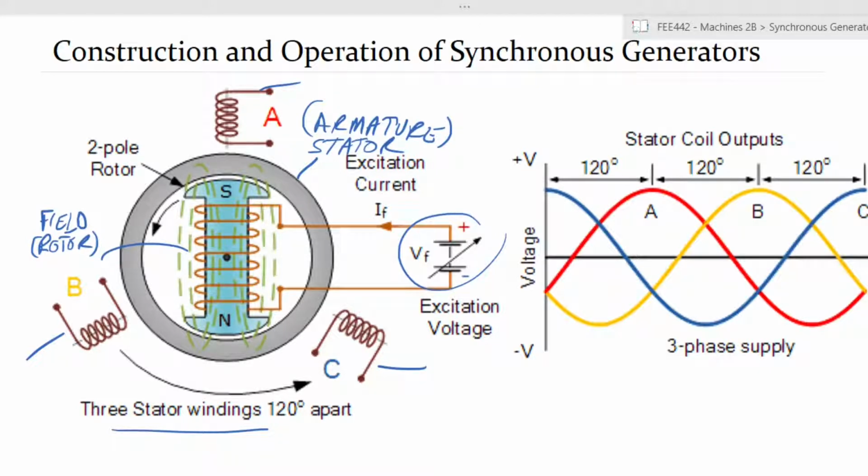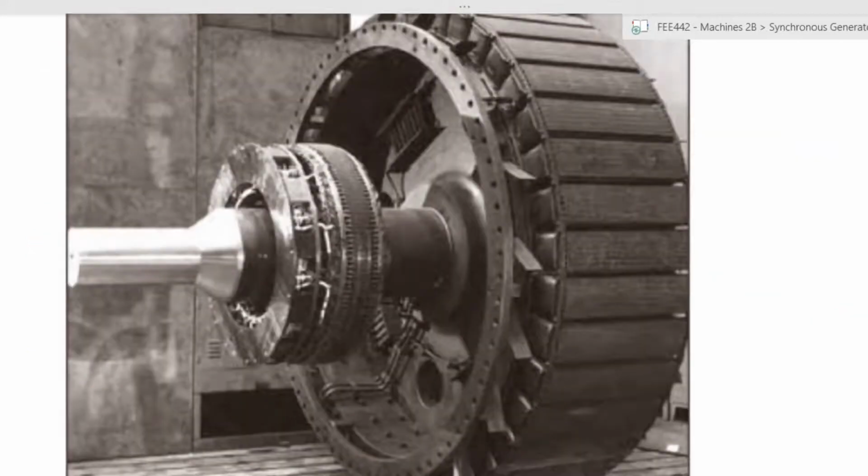So what you see on the machine is you have a 3-phase supply that is, as we have gotten used to, throughout all sorts of mains or 3-phase. It is just a normal 3-phase supply, bearing in mind the fact that the windings have been placed 120 degrees apart from each other. Generally the windings have a short cylindrical base, and you would have salient poles. That is, they are not a cylindrical rotor, it is salient poles. Each of these represents a pole that is providing magnetic field to the machine.